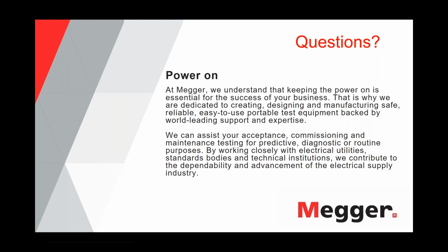Obviously you can do tan delta on EPR cables. The guideline, the IEEE 400.2, has different tables for different insulation type cables. And yes, EPR cable does tree. That's actually been known for quite a while. There are papers on that, and it does tree. It is not free from water treeing.